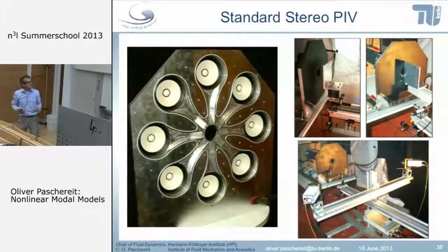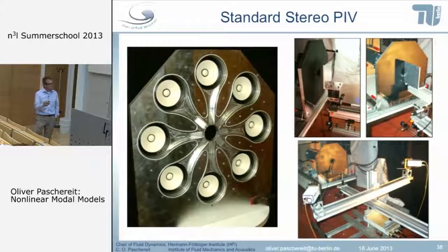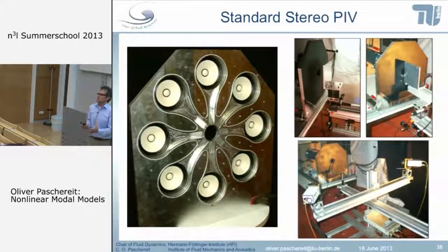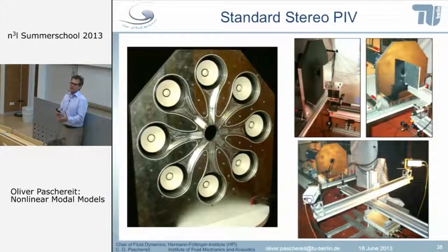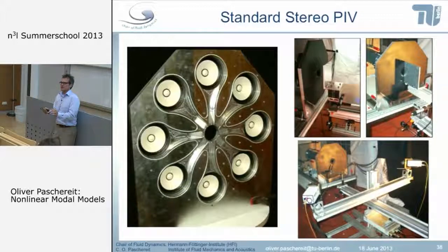And we had this basic idea, maybe it works also on swirling flows. There it does not work, but there fortunately other things work. But this basic idea was great because we thought, well, you can, for example, use this technique to improve mixing. You know that a triangular jet or a rectangular jet has better mixing and is less prone to thermoacoustic instabilities. So the idea was just by forcing it, because it's not easy to modify a nozzle or to put into a combustor a rectangular nozzle or a triangular nozzle.